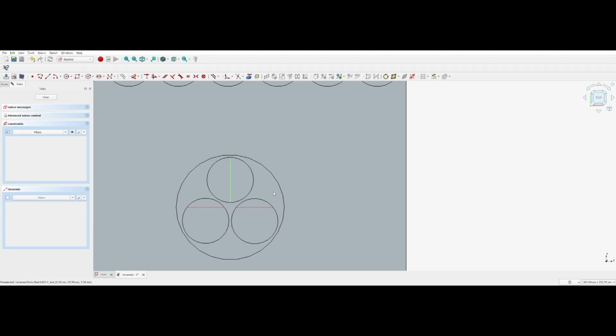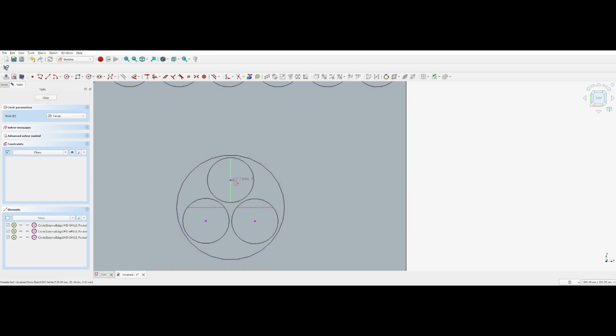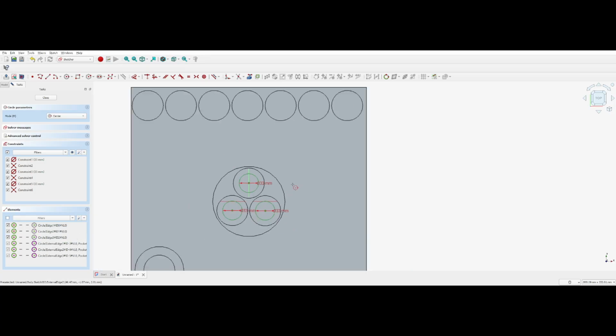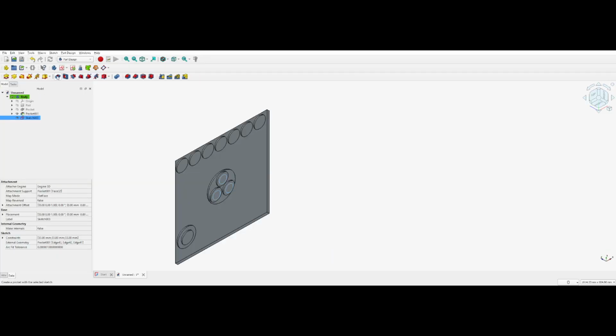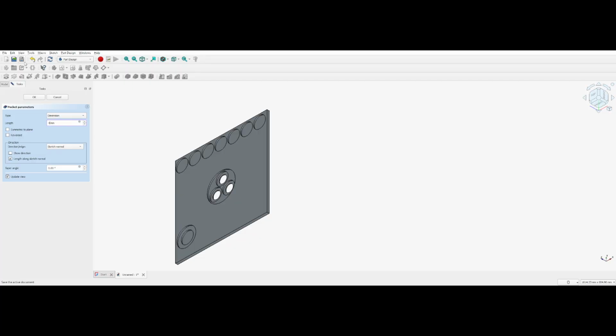And then you can do this, and now we don't have the center geometry just like before. We can go through and select external geometry for those, and then let's say that we just want some small bases to fit inside there instead. Close, and then we're going to pocket again, 4 mil, and you see we didn't compensate for the depth. That's fine, whatever.